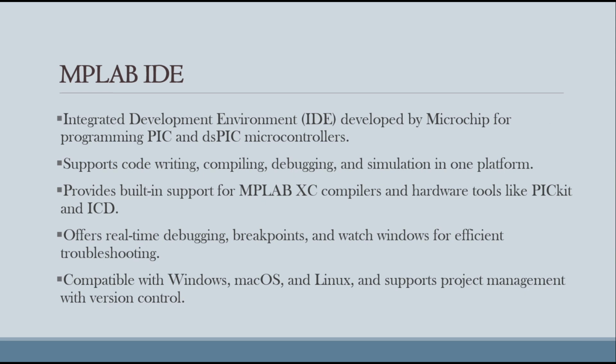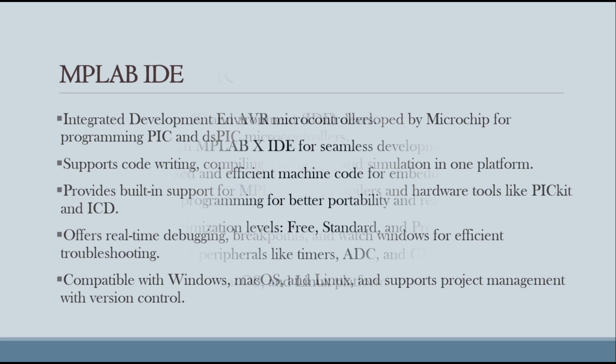Now let us see the development tools. First comes MPLAB IDE. IDE stands for Integrated Development Environment, which is developed by Microchip for programming PIC and dsPIC microcontrollers. It supports code writing, compiling, debugging, and simulation in one platform. It provides built-in support for MPLAB XC compilers and hardware tools like PICkit and ICD. It also offers real-time debugging, breakpoints, and watch windows for efficient troubleshooting. Compatible with Windows, macOS, and Linux, it supports project management with version control.